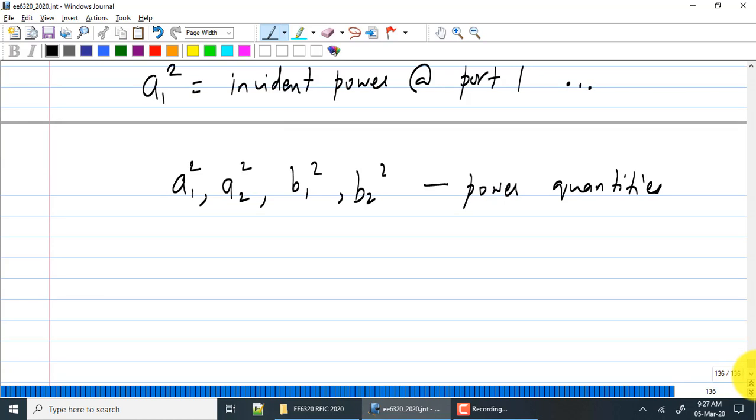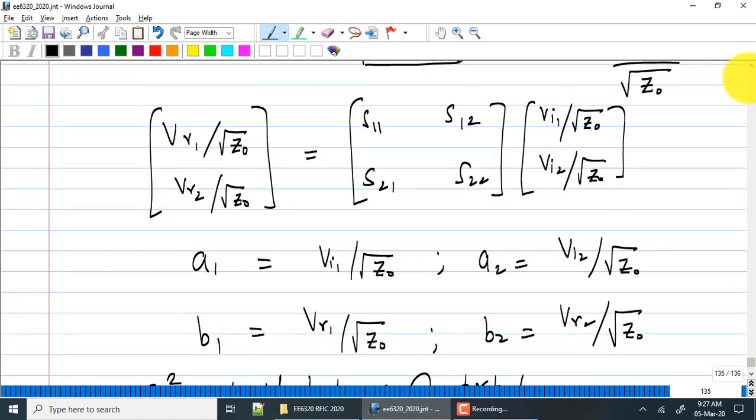If you had a perfectly matched system, Zin would be equal to Z0. Zout would be equal to Z0. The two-port will be loaded with Z0. It will be driven with Z0. A perfectly matched system, all impedances will be Z0. In our case, Z0 is 50 ohms.